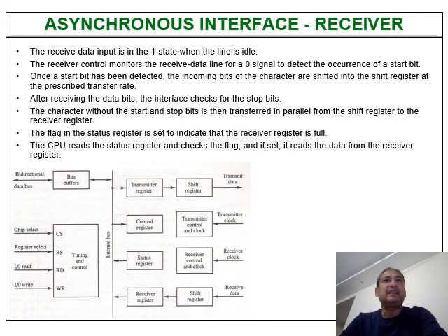When the system is acting as a receiver, the line by default is in the 1 state. As soon as the shift register receives a 0, it knows that it is now receiving a particular character. Then it starts accepting the data. It accepts the 8 character bits and the 2 stop bits, so it receives 11 bits in total.